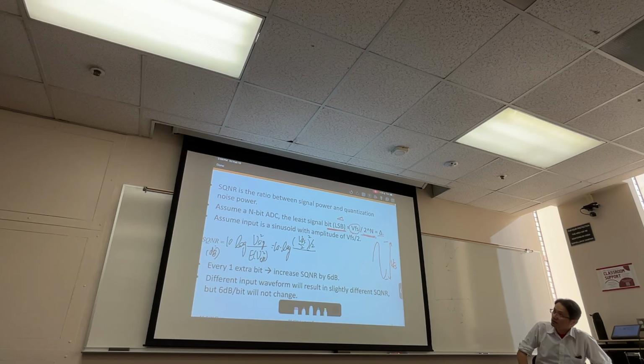Okay, next I need to know what's the quantization noise power. So what is that magic equation? Delta squared over 12. So what is my delta? VFS divided by 2 to the power of n, right? So that's delta squared over 12. Very good.